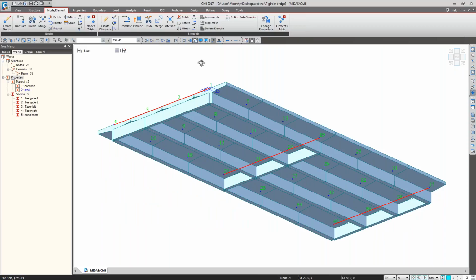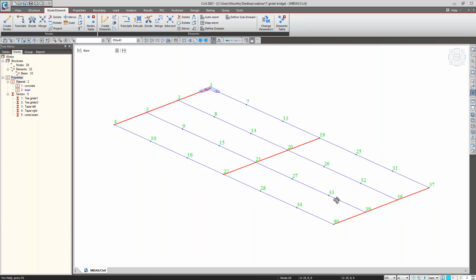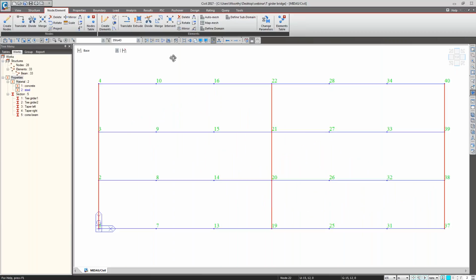And in general, we are connecting the slab for smooth load transfer from one member to another member. But in line geometry, we have connectivity only at 3 locations. So because of that, we will be using dummy members to make a smooth load interface.